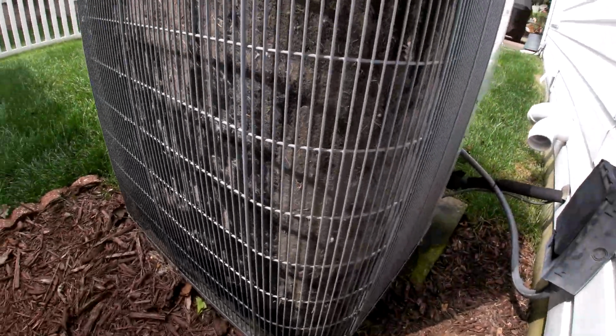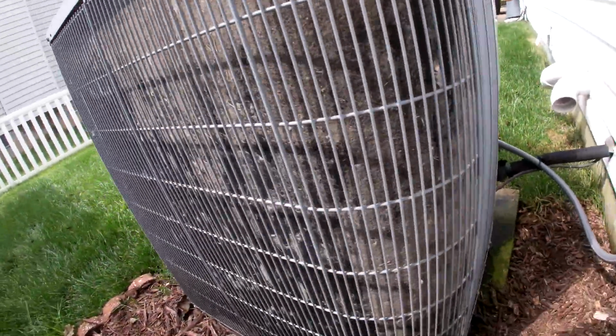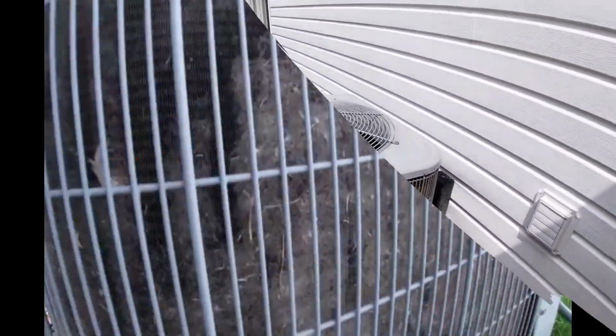In addition, your system must start up more often to keep your house cool, so it causes additional wear and tear on your capacitor here in the condenser unit and the capacitor which starts your heater blower motor. Worst of all, severe clogging of a condenser can cause your motor compressor to overheat and burn up its windings.